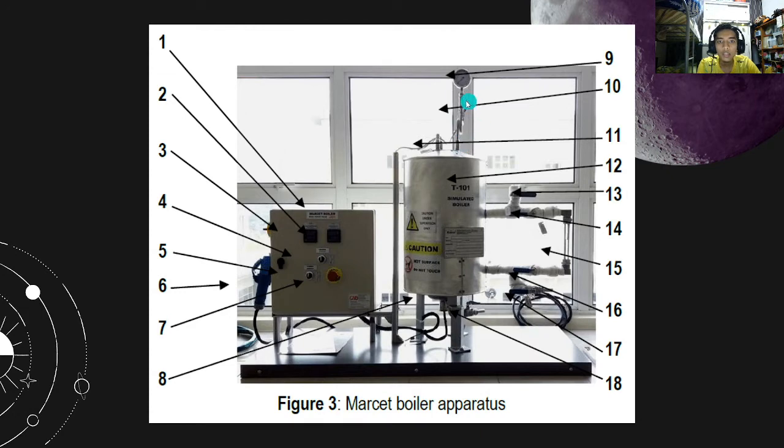When the temperature reaches 16 degrees, we will turn off MVB 102, and then we will take the reading of temperature from the indicator at every pressure interval of 0.5 bar from 1 to 10 bar absolute pressure, and then we will key the data into Table 2.